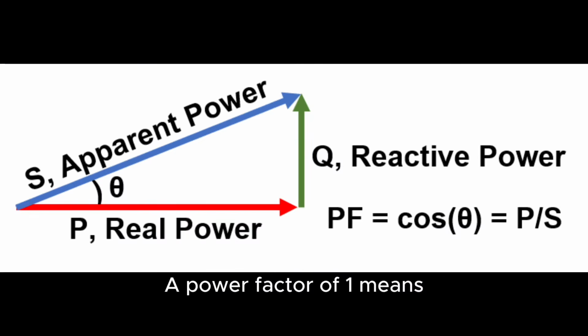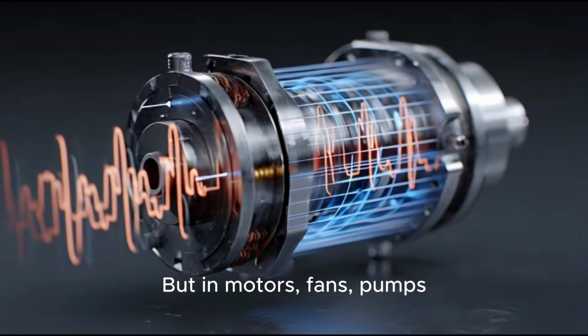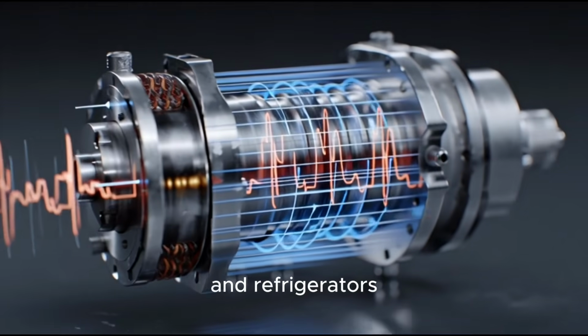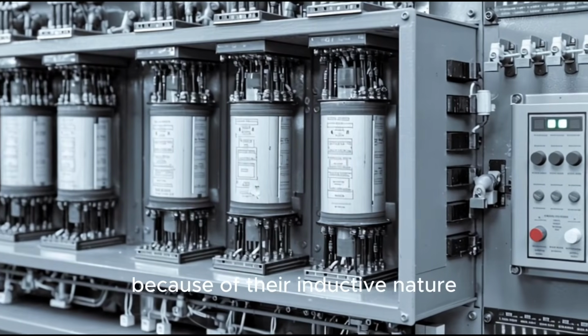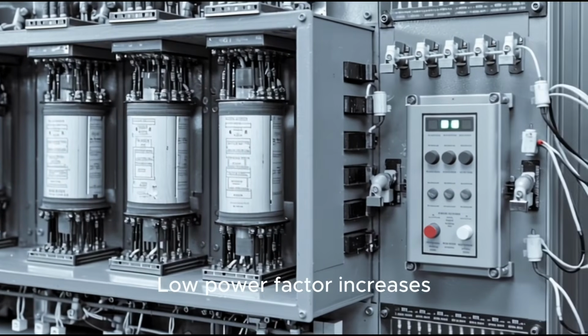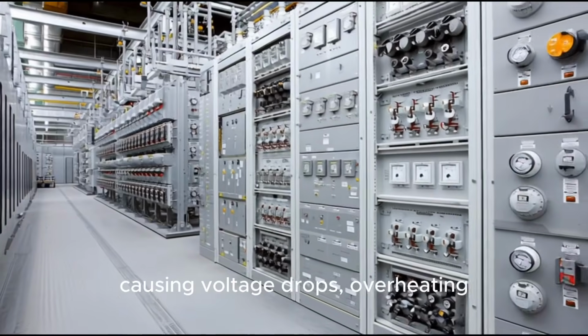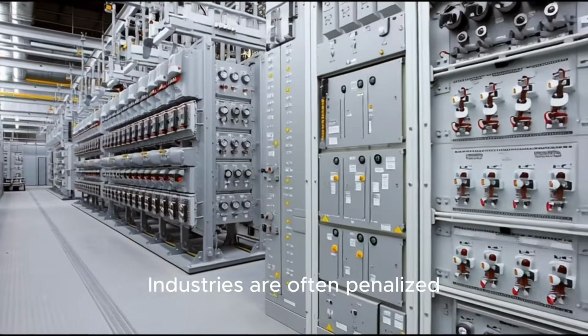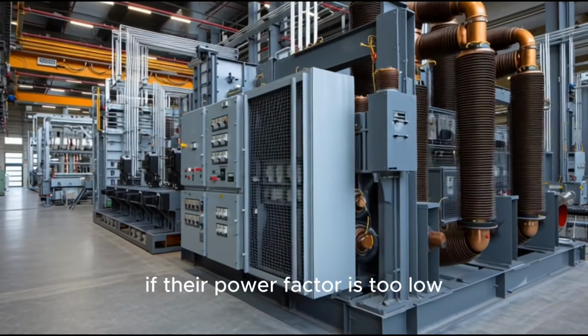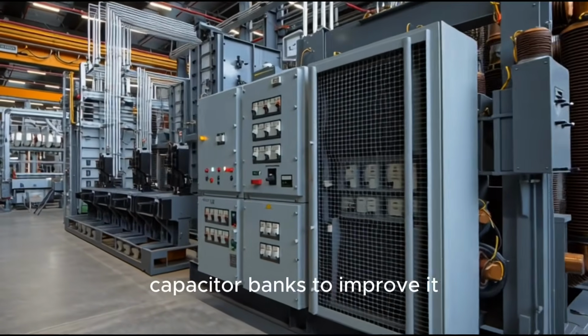A power factor of 1 means perfect efficiency, but in motors, fans, pumps, and refrigerators, power factor is usually lower because of their inductive nature. Low power factor increases current flow in the system, causing voltage drops, overheating, and energy loss in the wires. Industries are often penalized if their power factor is too low, so they install capacitor banks to improve it.